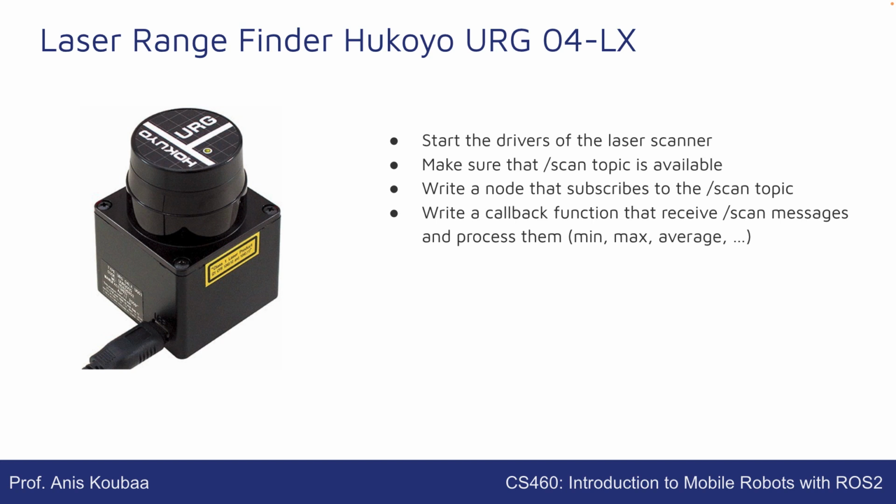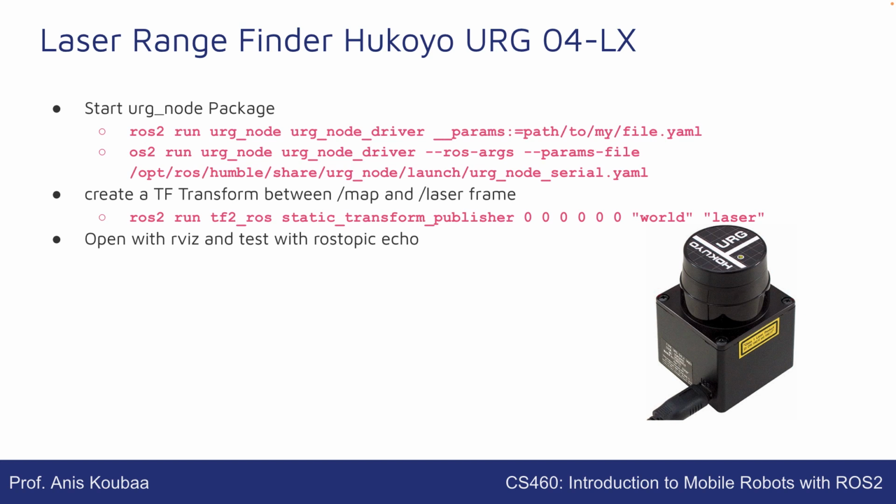Okay, so in order to work with this laser or any other laser, first of all, this is the process. Start the drivers. Make sure that the scan topic is available. Most of the lasers are going to publish on the scan topic, and we can write a node that subscribes to the scan topic. And finally, we have a callback to process these messages. So this is what I'm going to show in a moment.